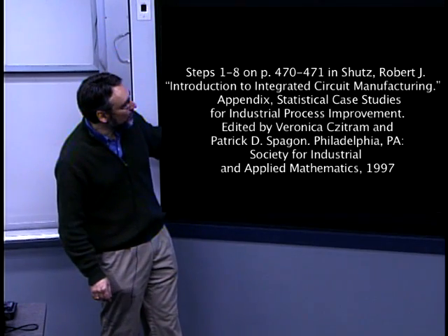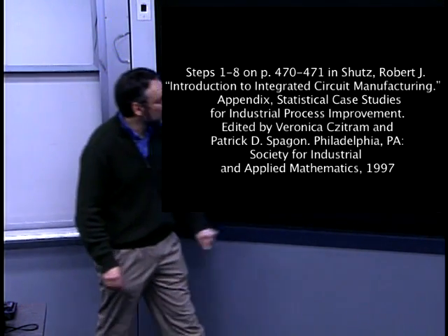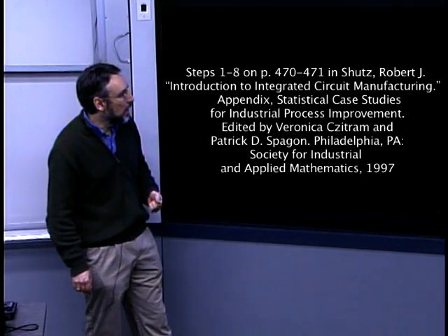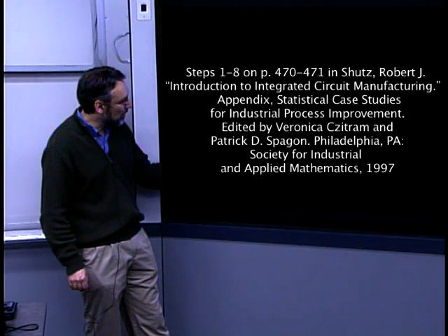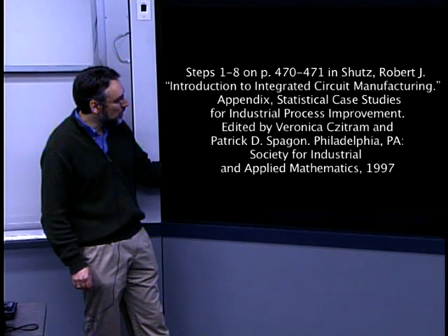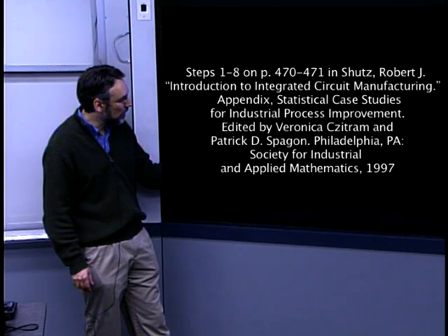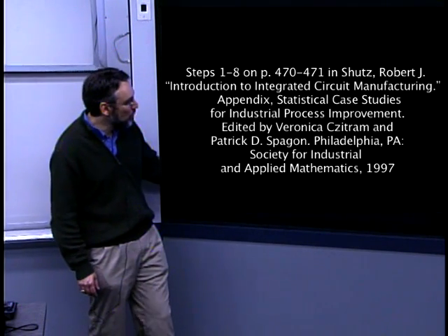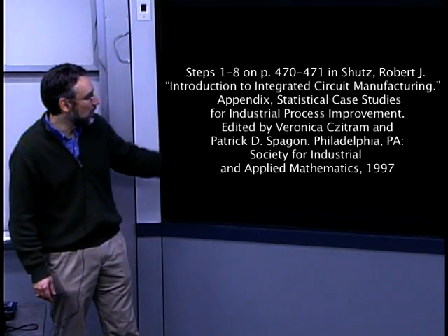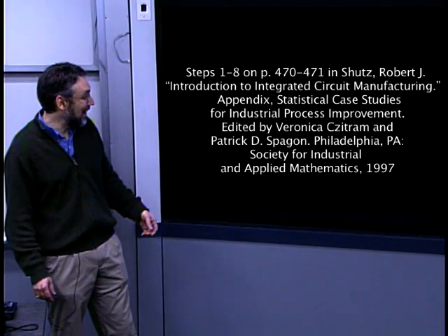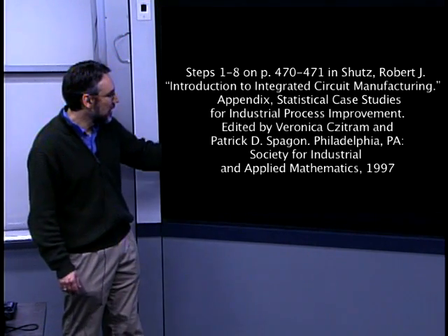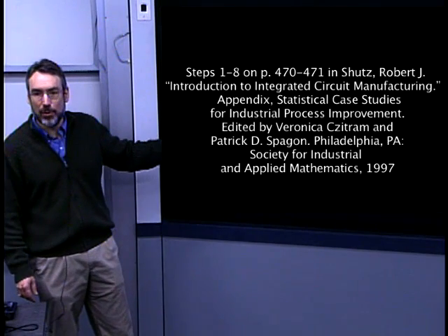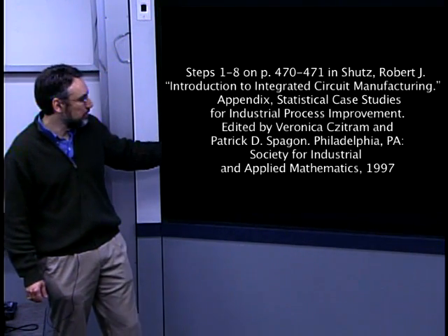So, still taking this at face value, we had the photolithographic sequence that imprinted onto the photoresist. We used that then to controllably change the permanent structure, the silicon dioxide, and then we remove the temporary photoresist using another chemical solvent, or in many cases another plasma etch, a plasma ash. Okay.